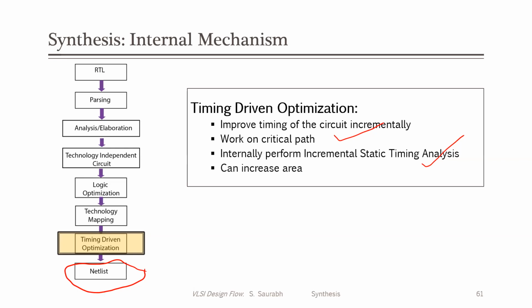At the end, you will have to manually change those SDC files. So typically SDC files are created by humans, right? If the tool generates it, it will generate a template only. It cannot infer on its own at what clock frequency you want your circuit to operate.